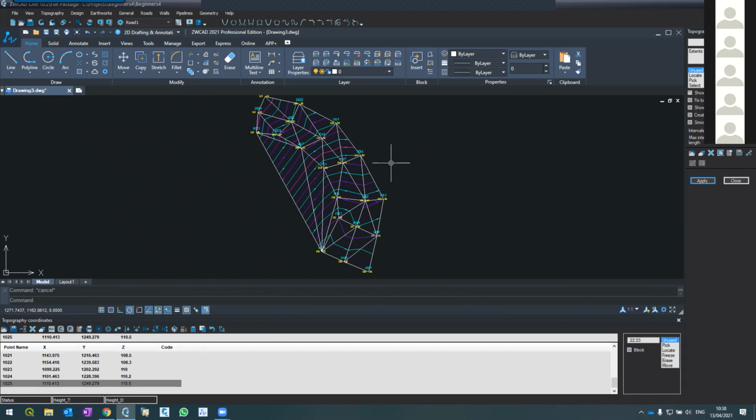So I'm saying to myself, software, I know that I as a surveyor don't want to create interpolation between points which are longer than 60 meters, or let's say 65 meters to be on the safe side, but I can play with it. Let's say 65 meters, and I press apply. See what happened. You see what happened?